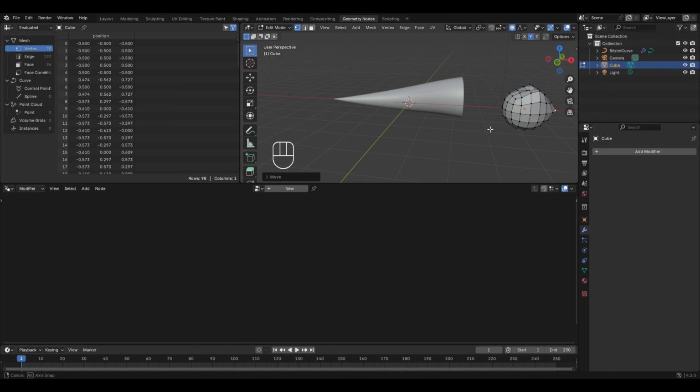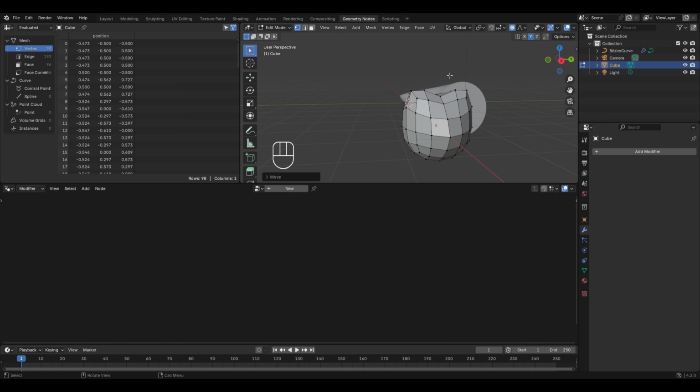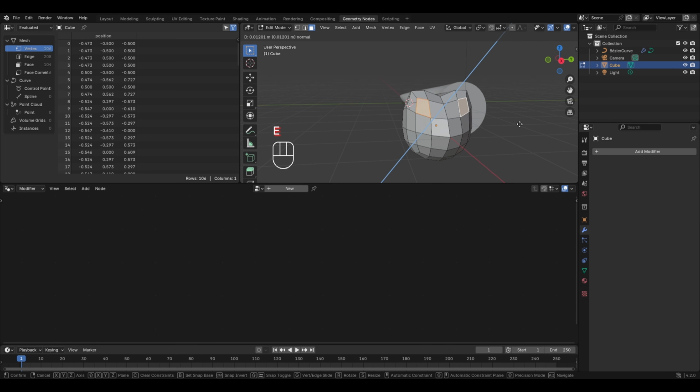Let's also go to the back of the head, select any vertex, press G, X and let's make it flat like this. Let's also increase the proportional size and then left click to finalize. Now let's make the eyes of the dragon. So first of all, turn off the mesh symmetry in the Y axis. Also turn off the proportional editing. Press 3 for the face select mode. Now for the eyes, I'll be selecting these two faces by holding the shift button. Let's extrude them inwards by pressing E and then move your cursor like this and left click to finalize. Now the basic structure of the head is almost ready.